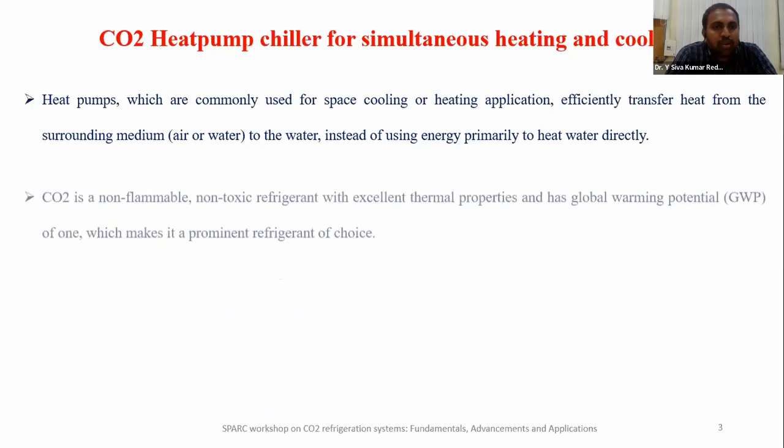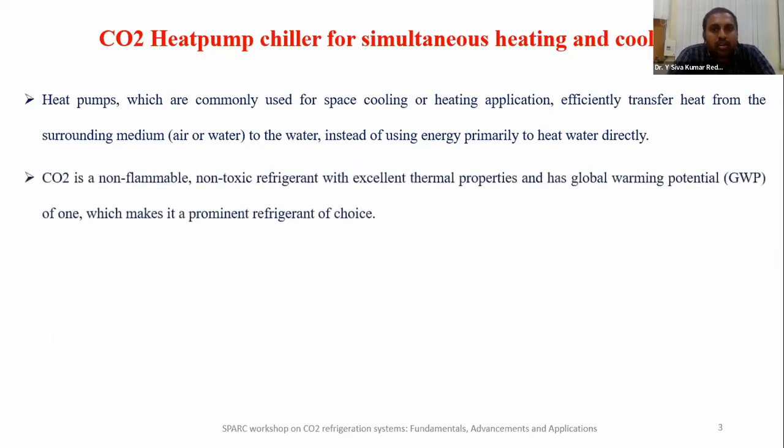heating applications. In these heat pumps, many refrigerants are being used, out of which CFCs are already phased out, and HFCs are being phased down. What we are left with are natural refrigerants and hydrocarbons. Among natural refrigerants, CO2 is an excellent refrigerant, which is safe, non-flammable, non-toxic, very cheap, with excellent thermal properties, and negligible impact. That means the global warming potential is 1, which makes it a refrigerant of choice.